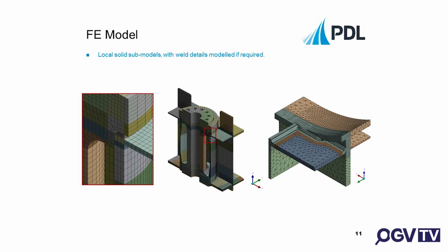So we've modeled the welds and we've modeled the corner detail because it's a weird connection that we can't capture otherwise. And obviously you can model the welds accurately. If it's a fillet weld, we can model the weld and then model a small gap between the plate and the next plate, so you get the actual load transfer through the fillet weld.